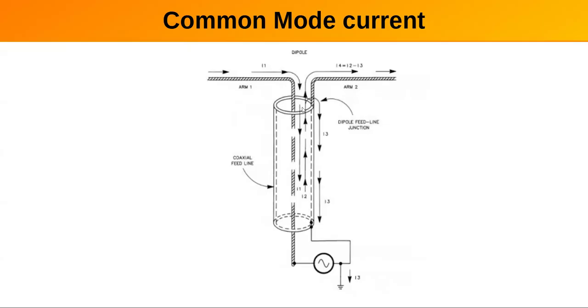Because of the charges and the electrostatic field between the inside of the shield and the center conductor, you've got equal and opposite currents flowing. So any common mode current that's different is going to have to travel on the outside of the shield. That's why you put a toroid around it. As far as the world's concerned, that coax just looks like a single conductor on the outside. So it's just like putting a bead on a wire, same effect.